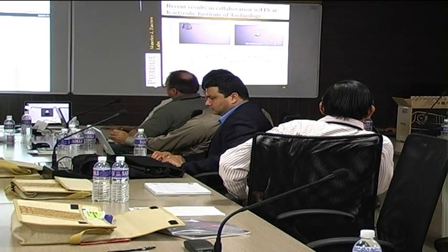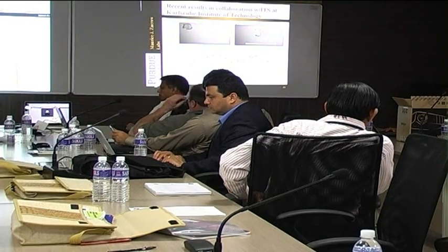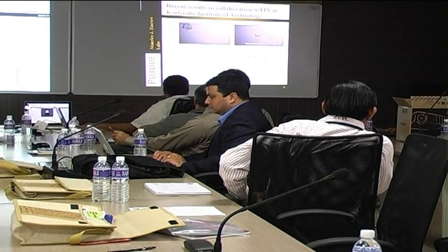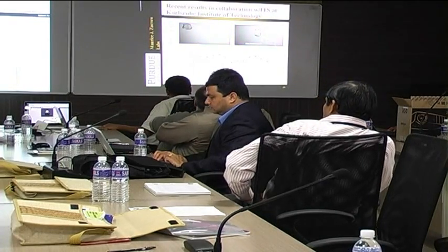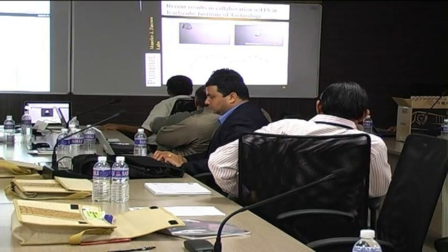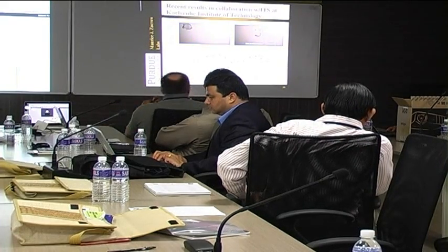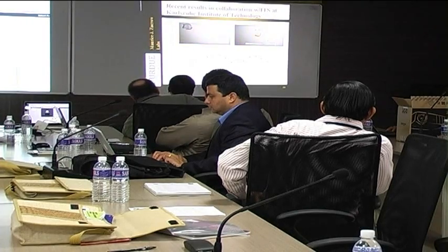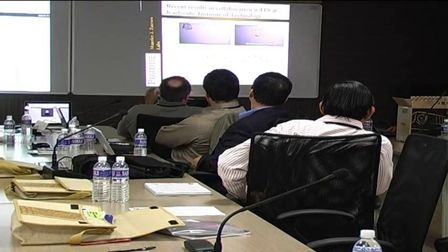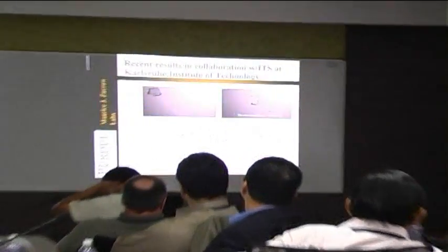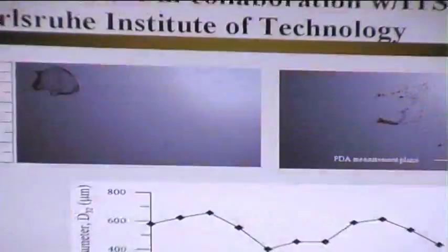So on slide 30, we have an image on the upper left of aerodynamic breakup as a bag breakup incident for a drop. And the image on the upper right is in fact the fragmentation products. You can see quite clearly the two significantly different sizes of fragments. There's an outline of the rim with a number of large fragments that perhaps supports Wirt's contention that the rim breaks up due to circumferential instabilities.